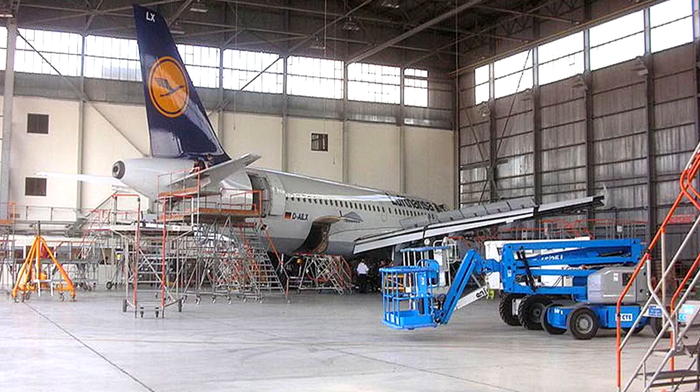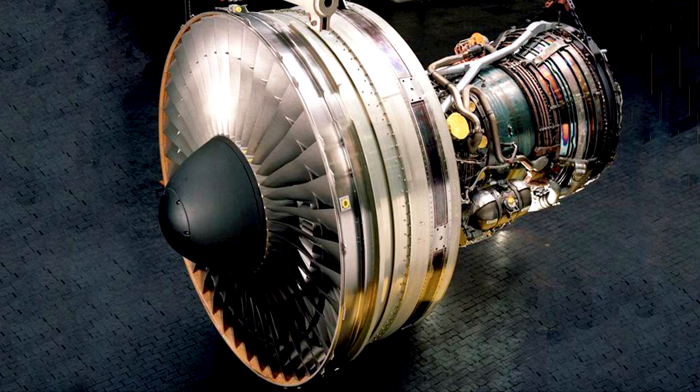For aircraft structures and components, there are two maintenance methods in common use. These are known as hard-time maintenance and on-condition maintenance. Hard-time maintenance is a preventative primary maintenance process. It requires that an appliance or part be periodically overhauled in accordance with the company's maintenance manual, or that it be removed from service. An example of this would be a part that must be removed from the aircraft after X amount of flight hours or calendar years for an overhaul, or disposal if it is a non-repairable item.